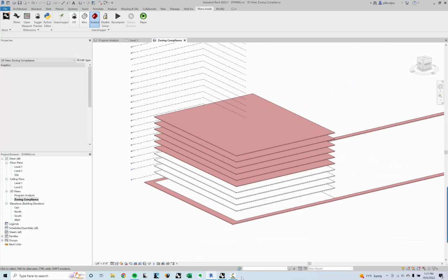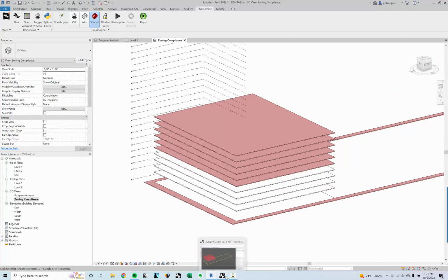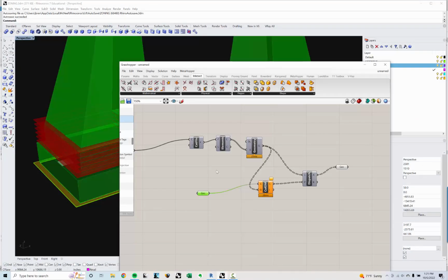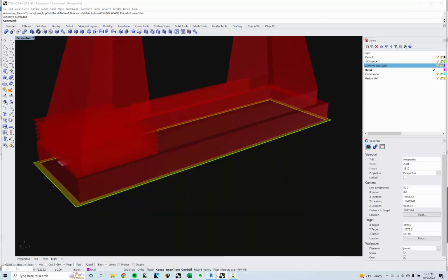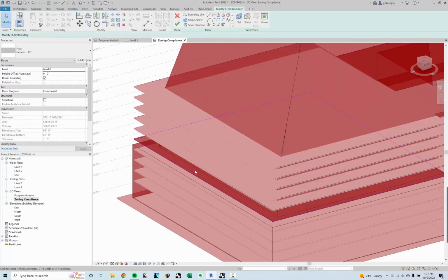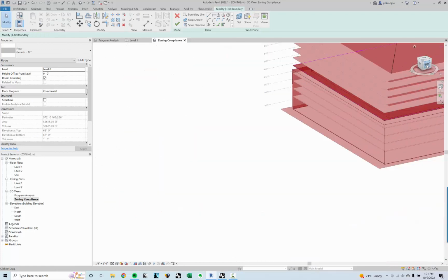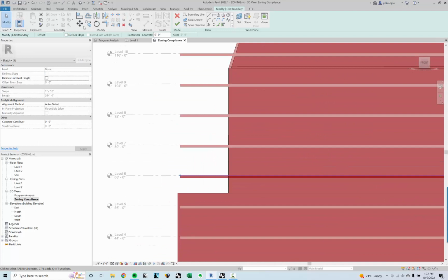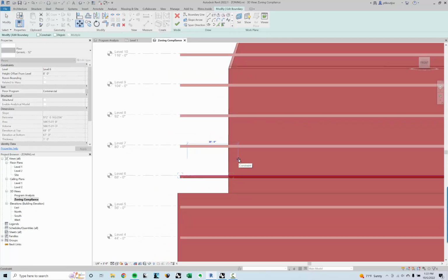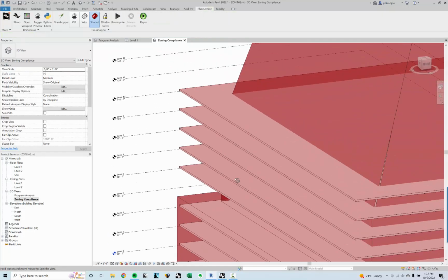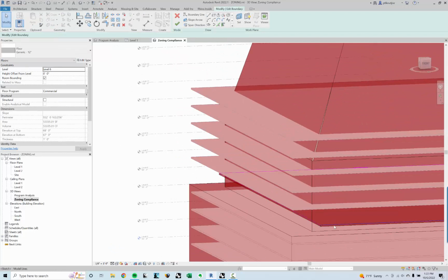And one other thing I can do is I can actually come back into Revit here, or in Rhino, turn this on, and start to edit these and use the zoning envelope as a guide. And I can start to, like, pull back this curve here so it's there. Click OK. Now that is going to be compliant. Actually, it's not, because it's still on the side here.